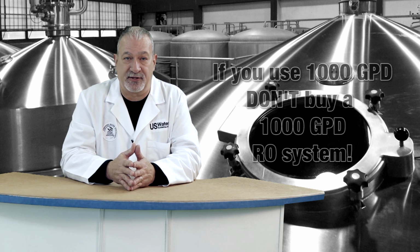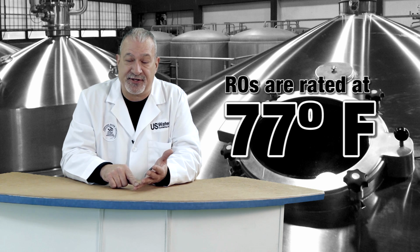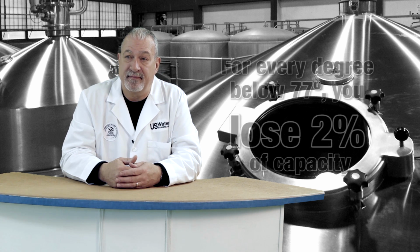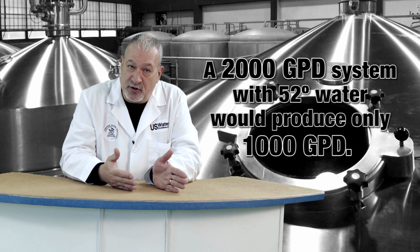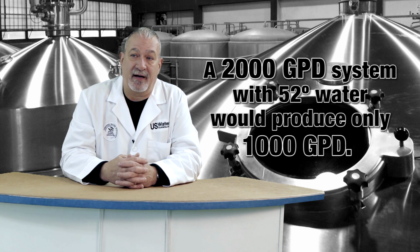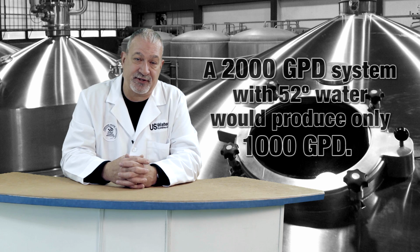What I mean by that is all reverse osmosis systems are rated at 77 degree Fahrenheit water. For every degree below that, you're going to lose about 2% of capacity. So if you had a 2,000 gallon a day system with 52 degree water, you're going to lose about 50%. So a 2,000 gallon a day system is only going to make 1,000 gallons a day. And you may say, well, if I need 1,000 gallons a day, then a 2,000 gallon a day system would be great. Well, would it?